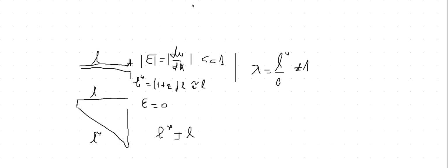So whenever you have very large rotation, you have to go to the large displacement theory. You can handle this with beams, plates, and shells. The geometrically linear theory is not only restricted to small strain, but also to small rotation. So applications are from computing slender structures, satellite antennas, airplanes,